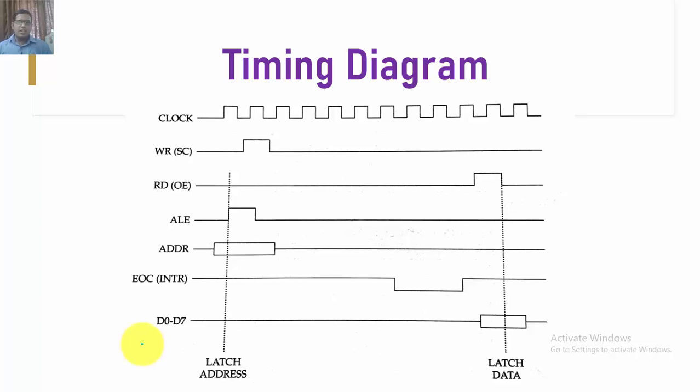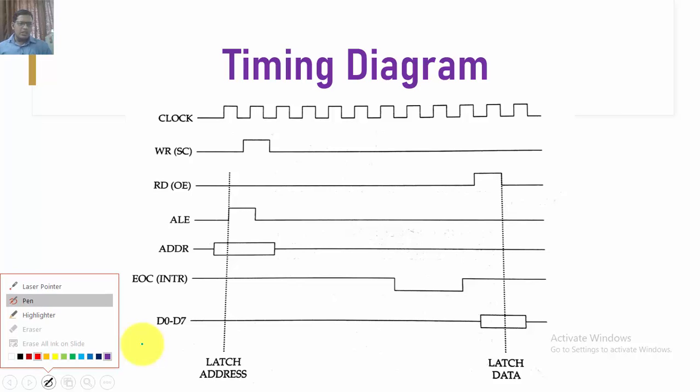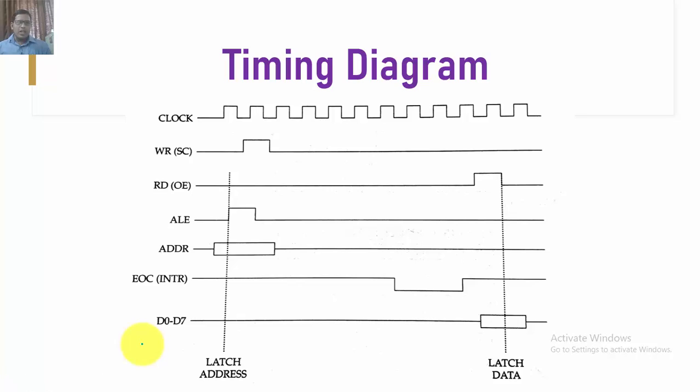So here I am with this, my timing diagram. So let us first find out the sequence of programming. So first of all, this is the first I am going to configure, that is the address line. This is for better understanding of how exactly the 0808 works, right? So first we are going to configure, and from the programming point of view, first of all I am going to configure the address line. Once I configure the address line, go with the address latch enable, that is ALE.